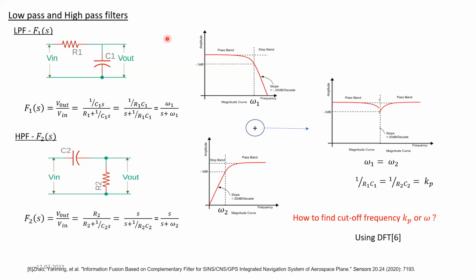So we can discuss this low pass and high pass filter. You might be seeing RC low pass and RC high pass filters. It doesn't mean that we are connecting a resistor and a capacitor to the data lines of the IMU sensors. It's just an interpretation of how we can formulate the low pass filter and high pass filter, just an interpretation.